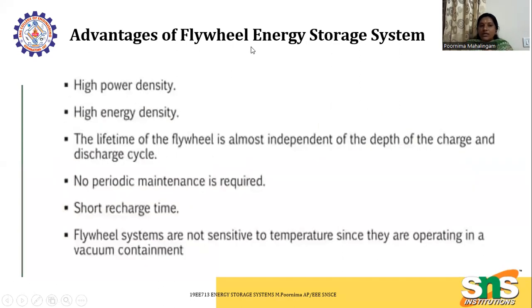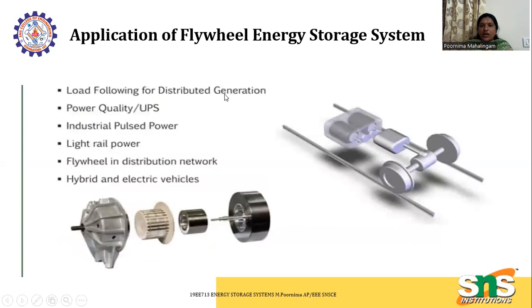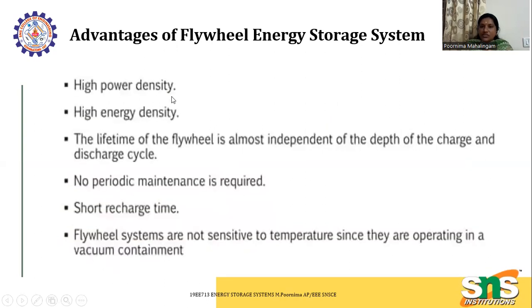What are the main advantages? High power density and high energy density, and the lifetime of a flywheel is almost independent of charging and discharging. The lifetime is also good and no periodic maintenance is required. Short recharge time is the main thing. And flywheel systems are not sensitive to temperature since they operate in a vacuum container.